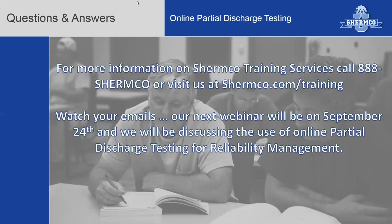Let's see, what is the best way to detect PD in electrical machines and to isolate the regions where PD occurs? In electrical machines, such as rotating machines, this is interesting. Online is actually one of the superior methods of trending PD in rotating machines because you have other dynamics taking place like vibration, movement, thermal dynamics, and you will actually uncover more possibilities of degradation in an online than in an offline experience.